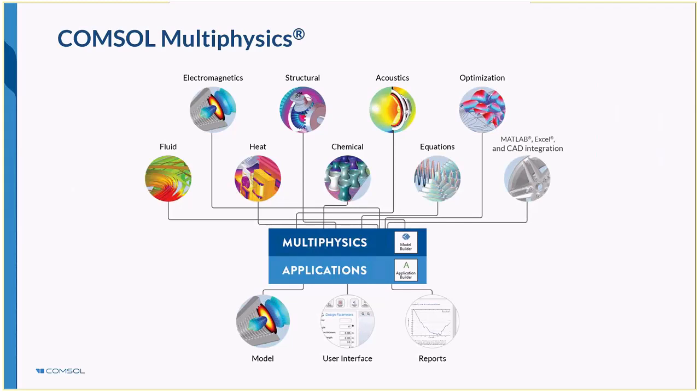The main advantage of the COMSOL multiphysics approach is that it allows the inclusion of many different equations and types of physics to be amalgamated together into a single model with a common user interface. And this approach is advantageous in electrochemical systems where the physics of charge transport and mass transport are going to be linked. So for a corrosion simulation, we might be interested in perhaps mechanical simulation as well, if we're investigating stress corrosion processes. So this is where we can link our structural physics together with our chemical physics.